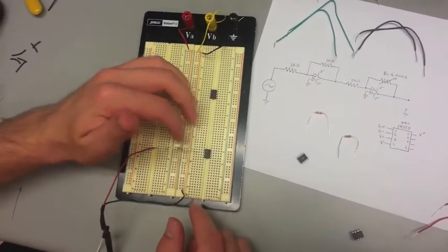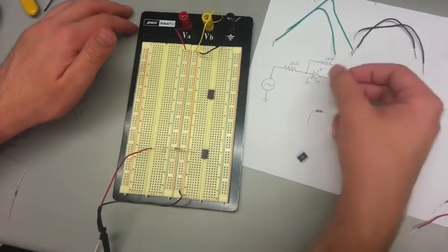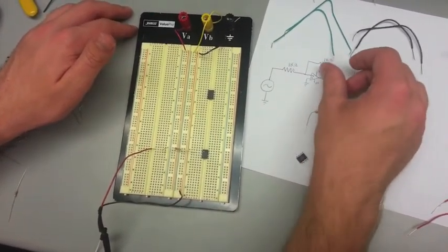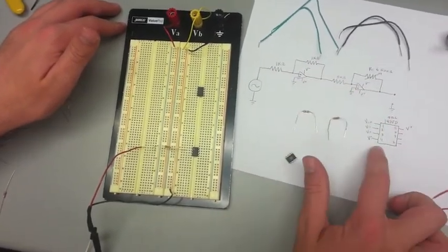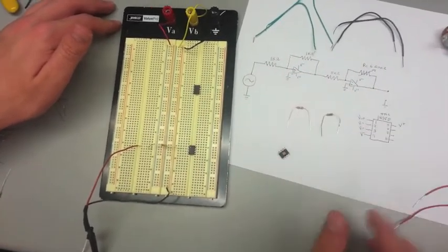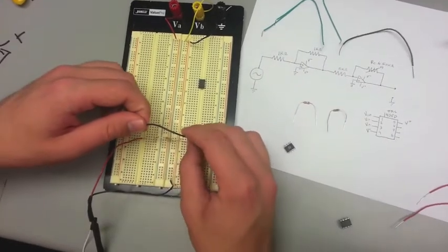And so it goes across that 1K ohm resistor into the V negative input. And then you'll see the V positive and V negative have been marked, as well as the ground, and right now we will complete that process. The V positive is on pin number 5, the V negative is on pin number 4, and the ground is on pin number 3. We will note ground by black, and so we go to pin number 3,